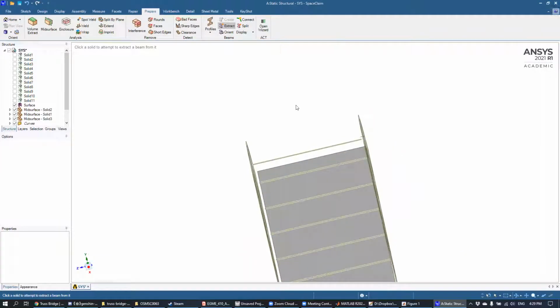Thankfully, Ansys actually has an automatic feature to detect things like this and then automatically extend them to make sure that they hit your geometry, right? That tool is this one right here. If you go under Prepare, and then to this button called Extend, and you read the tooltip for Extend, what this does is it extends surface edges or sketch curves up to the nearest intersecting body.